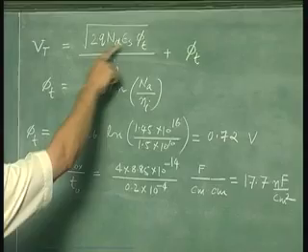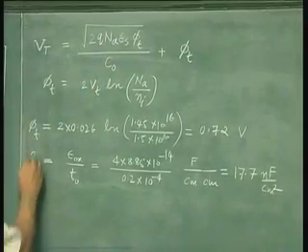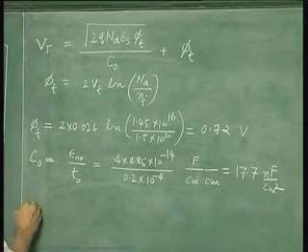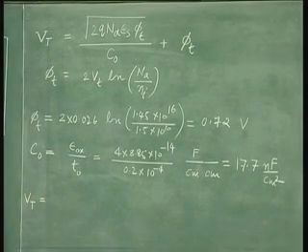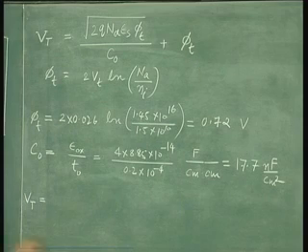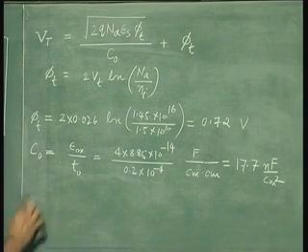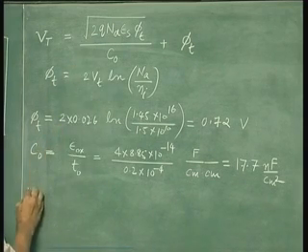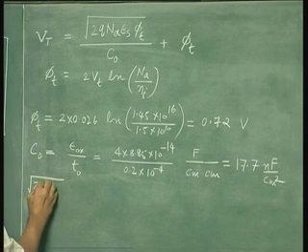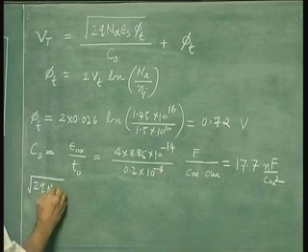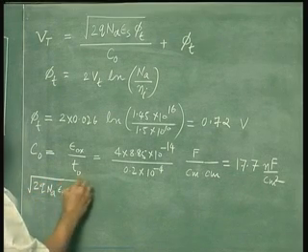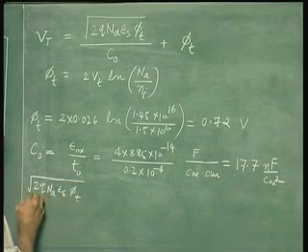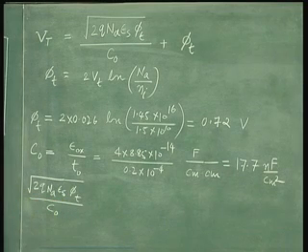Next we need to calculate the numerator of this equation. So now we can write Vt is equal to, or let us just calculate this term, square root of 2q Na epsilon s into phi t upon C naught.